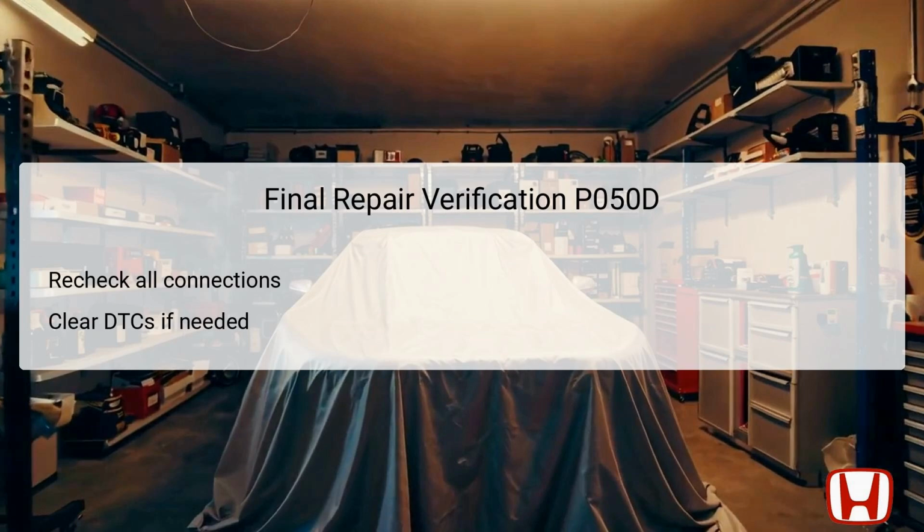After confirming that all components related to the PGM-FI system are operating effectively, perform a final idle test to validate that the cold start issue has been resolved. Pay attention to how the engine behaves during cold starts, ensuring that the idle remains stable without fluctuations.